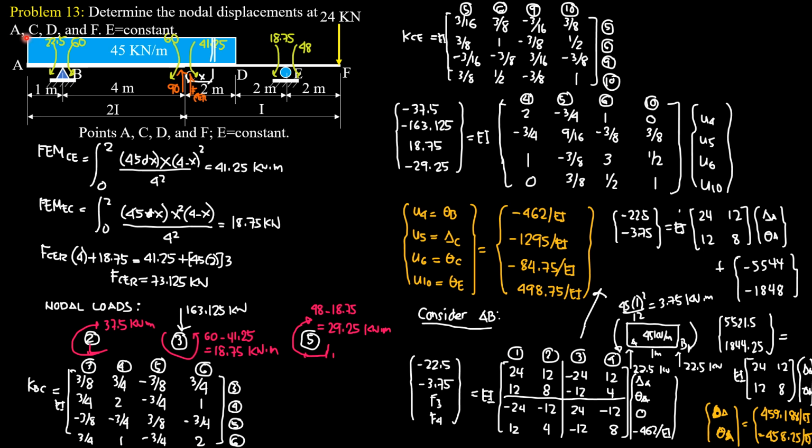at one time, the displacements at A, C, D, and F, because at A there are 2 unknowns, vertical and rotation. At C also another 2, at D another 2, and at F another 2. So that will make it 8 unknowns. So it cannot be handled by the portable calculator allowed in the licensure exams. So instead we consider B, C, and E first. At B there's only one unknown, the rotation. At C 2, vertical and rotation, and at E rotation. So that makes it 4 unknowns.